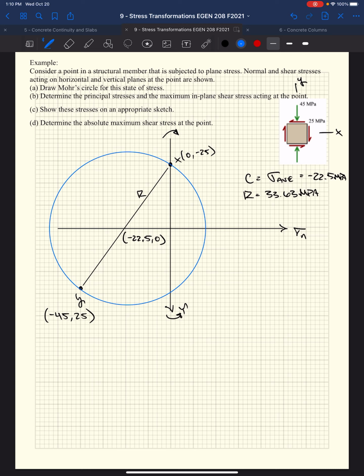So in this case, this stress block is as if we had a compressive force on the top of this plastic pipe, right? And we were twisting it at the same time. And we looked at the stresses by just cutting a piece off of this column, right? We just cut it off and we were looking at the edges of this column. We would have a shear stress and a normal stress like we do. Well, those principal stresses and our maximum shear stress are going to be at a different orientation, right?